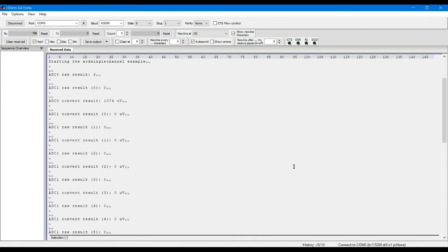Why would it? Because your ADC 0 thread was spawned, it measured the raw value. This 3 is nothing but a kind of floating value, because I haven't connected the launchpad pin, so it is some floating or leakage voltage which it is measuring.